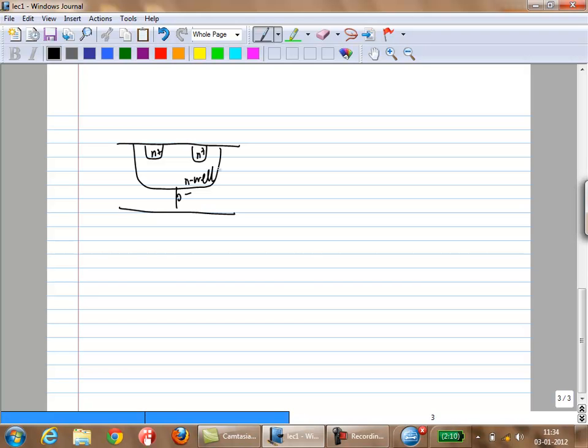Okay, an N-well resistor could look something like this. Obviously the length is given by this parameter. Let me call these P1 and P2; those are the two nodes of the resistor. Why do you need these N plus diffusions? To make a good contact to the actual resistance. The actual resistance comes between these two nodes, but to make a good contact, you need N plus diffusions. The connection to the rest of the circuit will happen on metal.